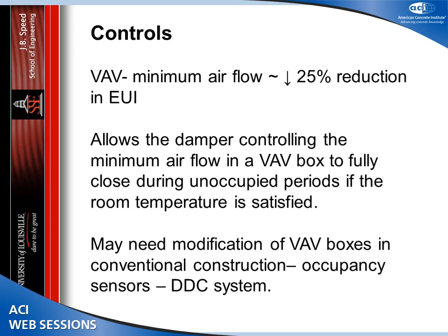The VAV minimum airflow, we could get up to a 25% reduction in energy use on that. And what that did was allow the damper controlling the minimum airflow to fully close. Typically, they're not designed to fully close, so that they get a minimum amount of air exchanges going into each of the spaces, which is required by code, but because they assume all spaces are occupied. And so that's a typical design practice, at least in the areas that we investigated.